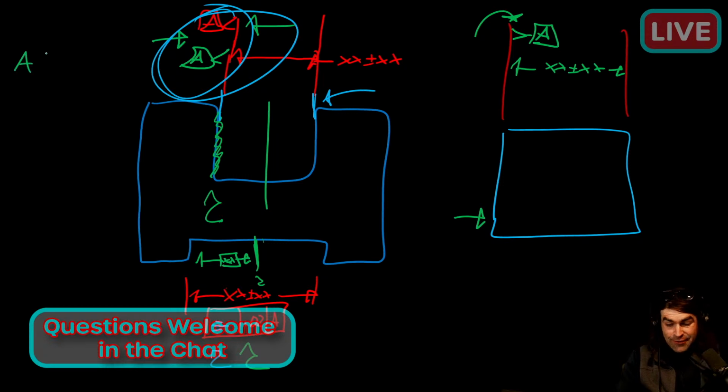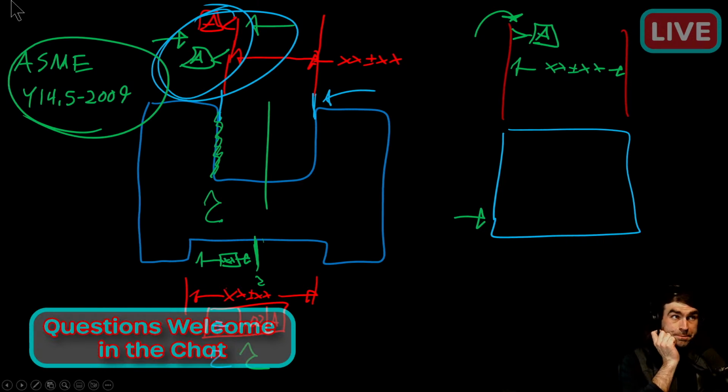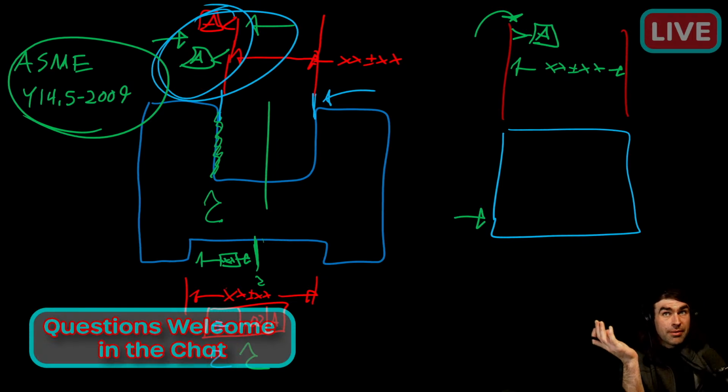If you're based in the U.S., just put ASME Y14.5-2009, if you don't have any other reasons to go with something else. It's not the newest version, but it's the most common version, and it's the one shops are going to be most comfortable with. Generally, I mean, there might be some shop that won't quote.